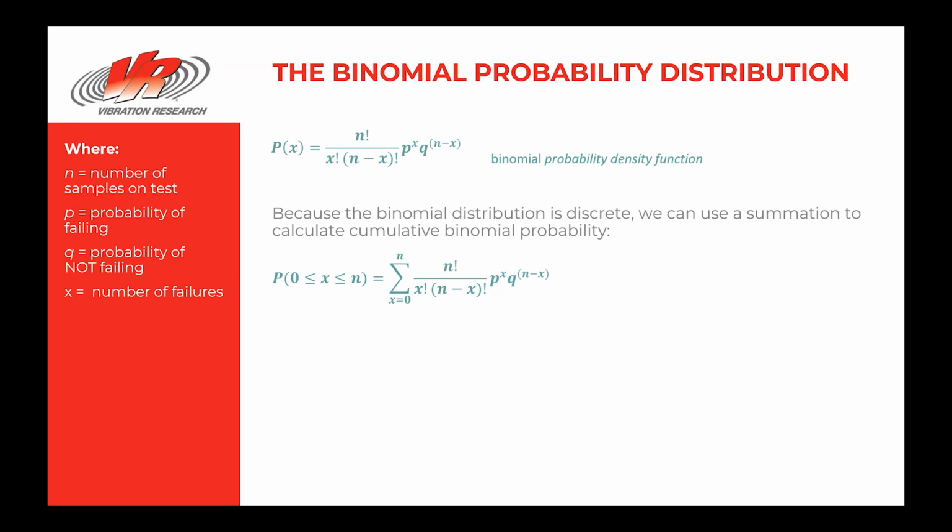And the probability of a failure is constant. So the probability of a failure on a given product for a particular failure mode, we assume to be constant, and we set it equal to 1 minus our desired reliability. So this is exactly what we have and what we need for a success run testing situation.